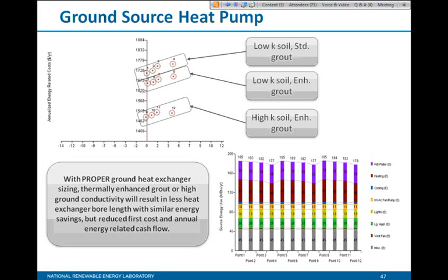Also, if a user is interested in seeing 30-year performance, or perhaps in an existing installation situation, you can use BEopt EnergyPlus to run one simulation and generate an energyplus.idf file, and then change the IDF file to a 30-year simulation period to see the performance degradation. Users can always contact us if there are any questions on that.